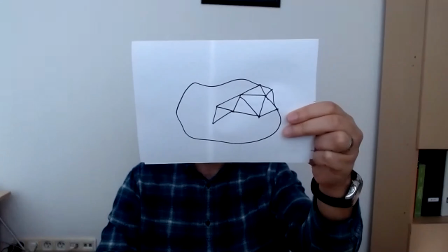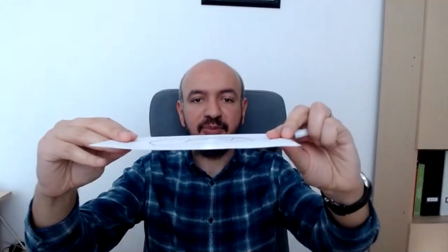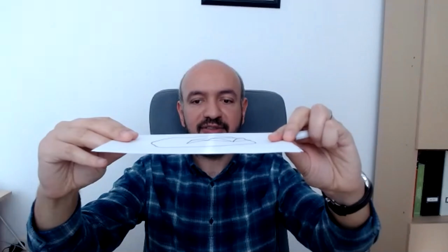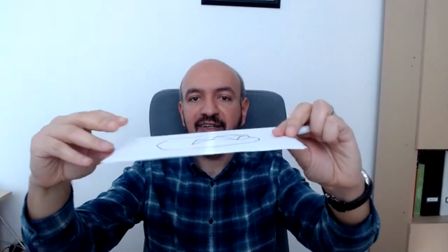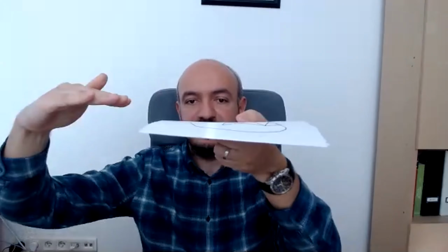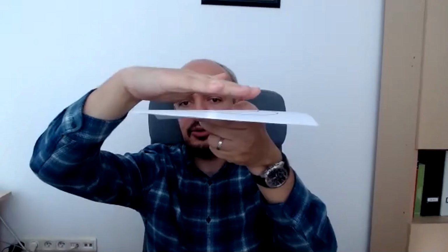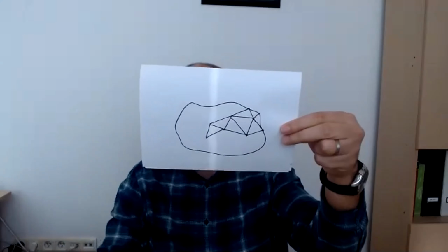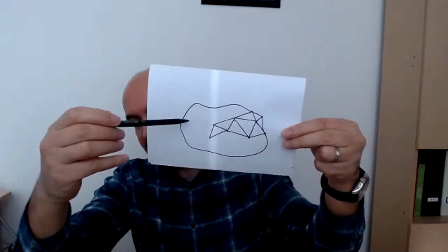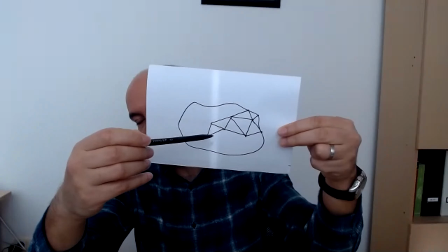So you see, we are assuming that this is the top surface of the part, okay? Since the fourth case states like that, you have a slicing plane, and the slicing plane is matching with your top surface. So in 4.2, if you have some intermediate triangles, you can simply ignore them.